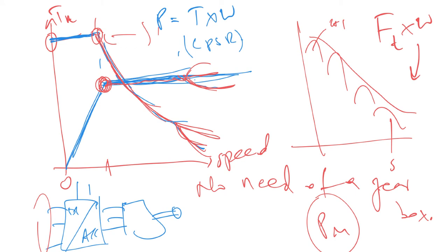Right. So this is how one moves from the wheel to the electric machine. And once you know the power rating of your machine, remember that's the output power. Then the question is, what's the efficiency of your machine? And once you know the efficiency, you should know the input power. And once you know the input power, boom, you know how to size the electrical elements, what your electrical elements should be. All right.